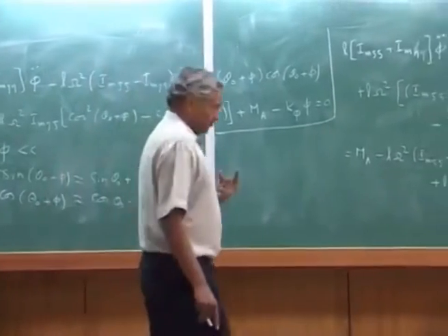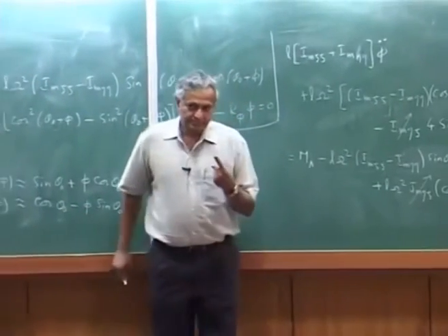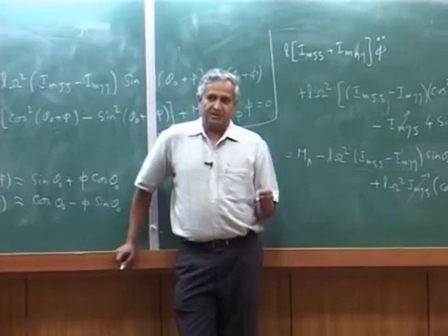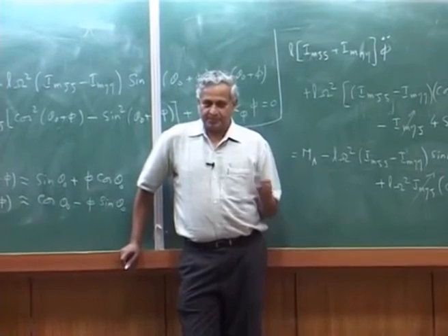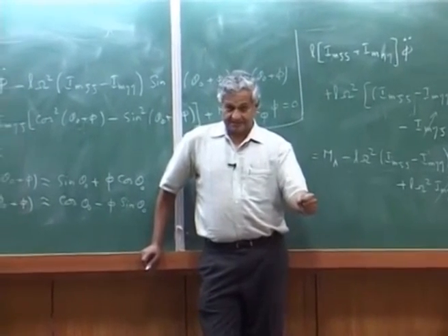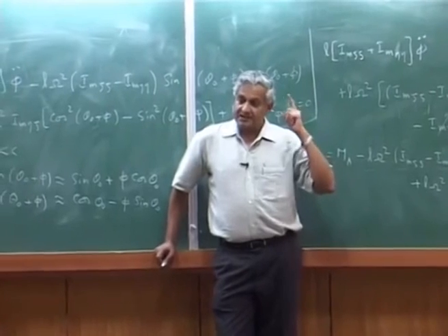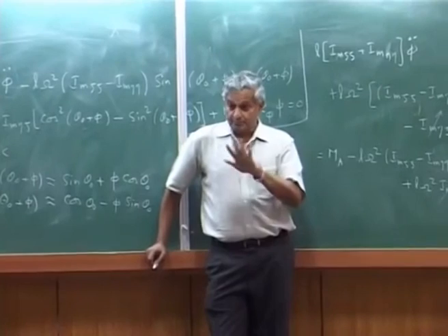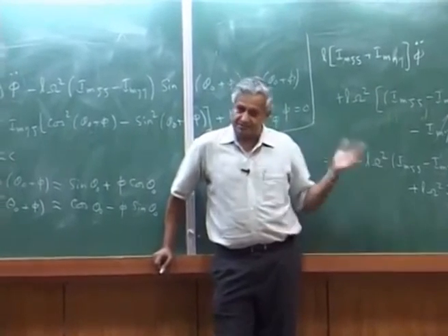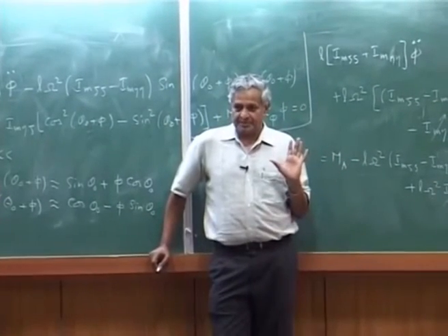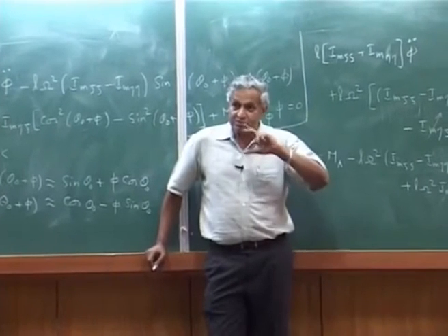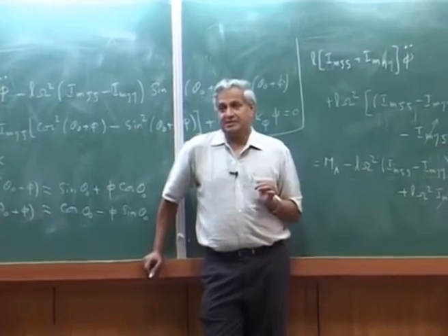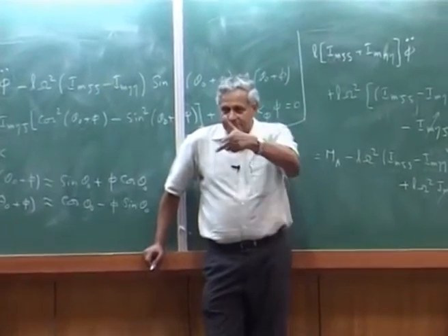Okay, so usually what you set, the pilot may give a command. This is my pitch angle. But what the blade experiences is not the same. Just dynamics, no aerodynamics. When aerodynamics comes, that will also change the angle of attack. But here, because of the elastic twist, you will find a loss in the pitch angle.